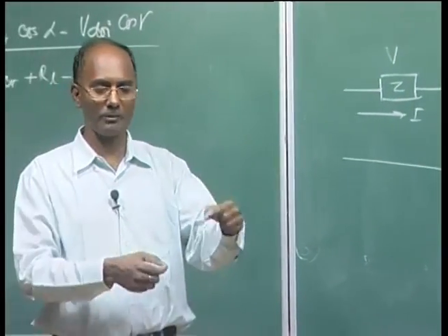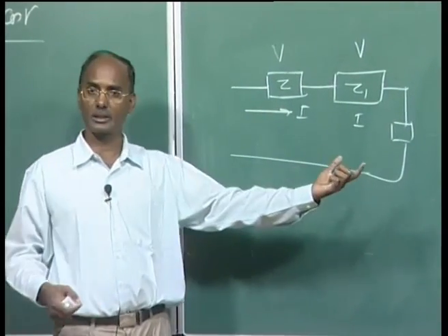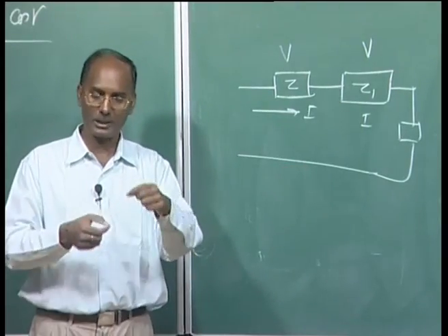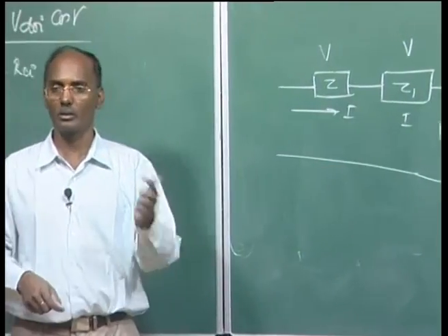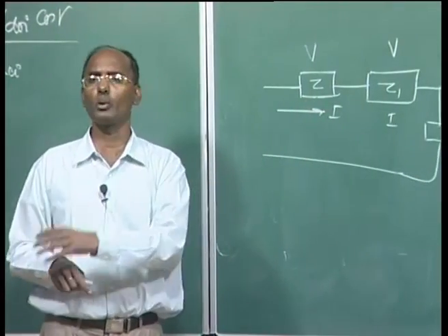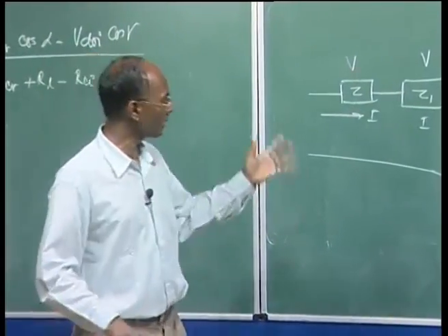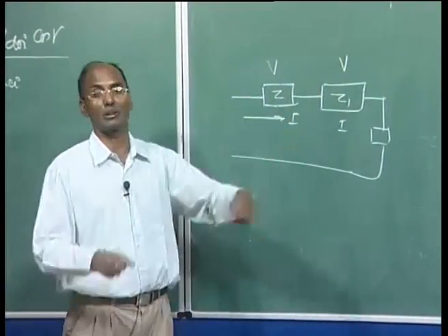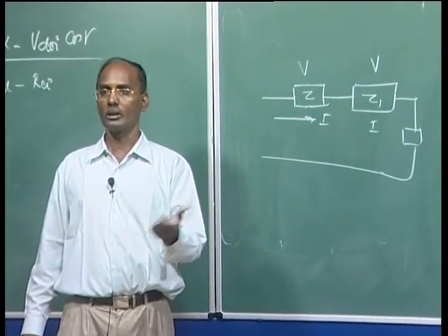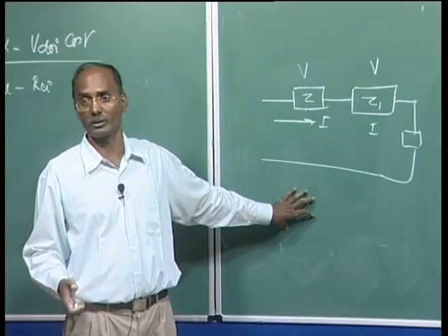But in AC, constant voltage is always preferred, and we found that in the AC system constant voltage is better than the series one. So the series scheme was used in the beginning when there were very small loads and DC generators, but now it is not so. Even with DC generators we are connecting the same type of parallel loads. Especially for small voltage loads, the constant voltage scheme is more efficient.